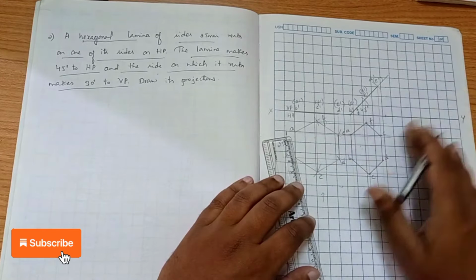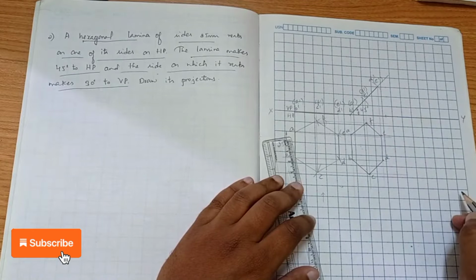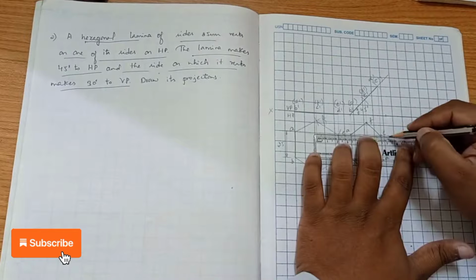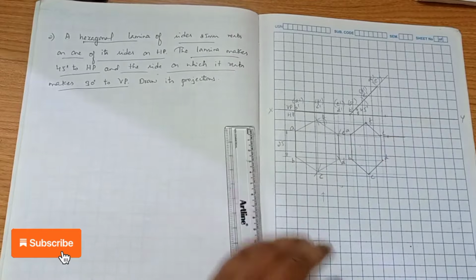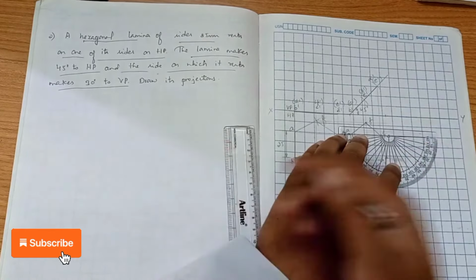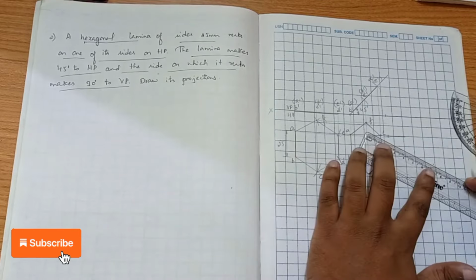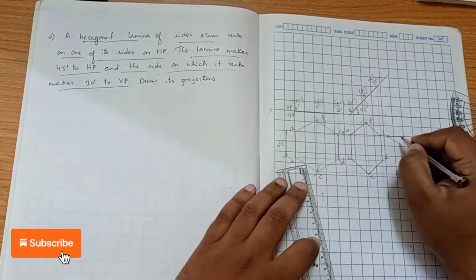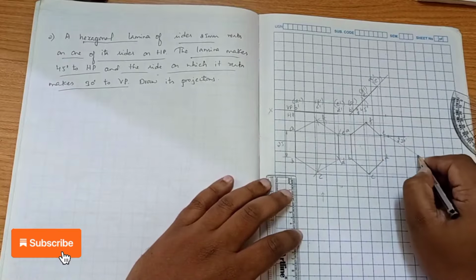So here in this thing, we can draw an angle line here also, or we can take here and we can draw a parallel line here. So by taking a parallel line here, we can draw the angle line here also. I'll be drawing a parallel line here, so that we should avoid the merging of the lines. Okay, so angle to VP is 30 degree, so I mark for 30 degree. It is 30.